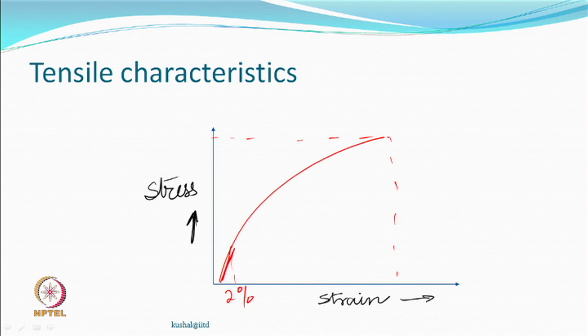And if you look at the modulus of the yarn compared to the parent yarn, this modulus can also be relatively less. So, this may be a softer kind of a material, and so one can work around and determine that also. But tensile strength etc., we should be worried, not exactly worried, but we should measure it correctly because the loss could be quite high. This type of test can be performed on a normal Instron type of a machine, tensile tester.